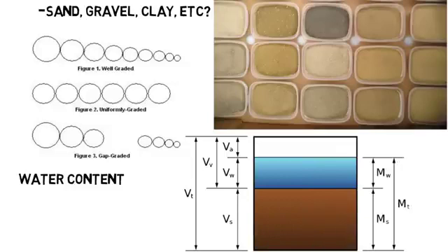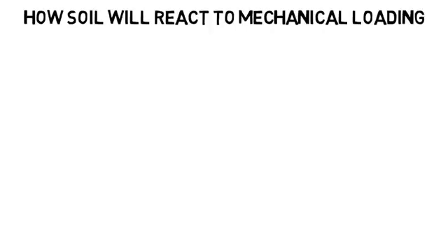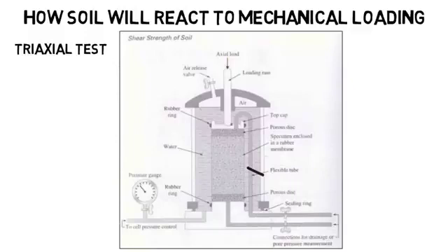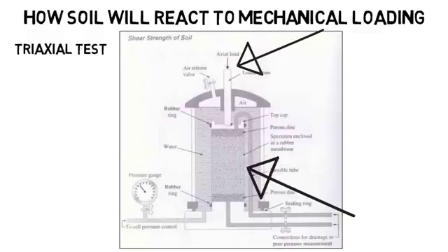But most importantly, you'll measure how the soil will react to mechanical loading or to different forces acting on it. So you might perform a triaxial test, for example. Too complicated to explain for this video, but essentially you put the soil in an enclosed area and apply a force or load to the top, which pushes down on the soil. Then pressure sensors measure the pressure at different points to see how the soil is being affected.